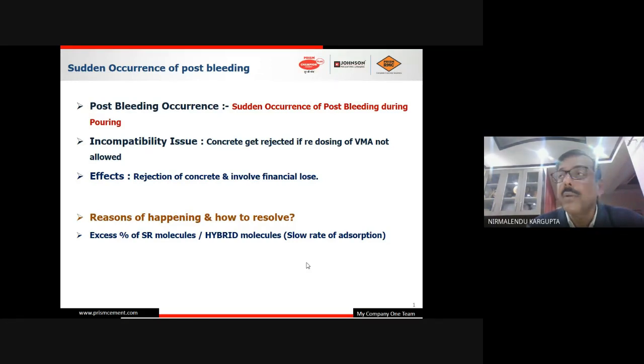एक्सेस परसेंटेज ऑफ एसर मॉलिक्यूल्स, पहले बताया था ना कि एसर मॉलिक्यूल्स का जो एड्सॉर्प्शन फेनोमेना है वो स्लो है, वो पहले वो नहीं किया, मतलब एड्सॉर्ब नहीं हुआ सीमेंट पार्टिकल पे. वो 1 घंटा बाद 2 घंटा बाद जैसे ही वो एड्सॉर्ब हुआ, कंक्रीट को ब्लीड कर दिया. मैंने देखा इनिशियली ब्लीडिंग नहीं था, 1 घंटा में भी ब्लीडिंग नहीं था, 1.5 घंटे से ब्लीडिंग चालू हो गई. ऐसा होता है इनकम्पेटिबल. सो रिजेक्शन ऑफ कंक्रीट एंड इन्वॉल्व फाइनेंशियल लॉस.